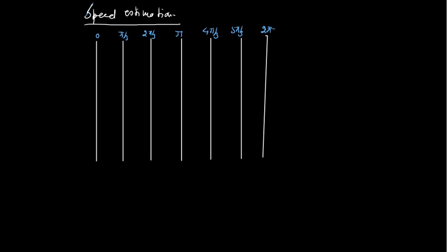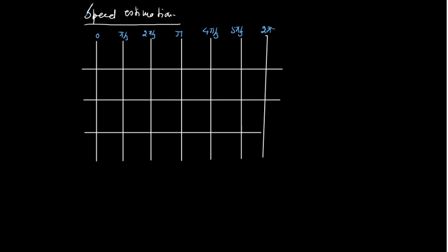Okay, now next we have to draw 3 Hall sensors: 1, 2, and 3. And how were our Hall sensors? You remember? One Hall sensor was getting high from here, you please see that high, and it was remaining high for 180 degree, and then it was becoming low, and then again it was low till the end of the cycle.